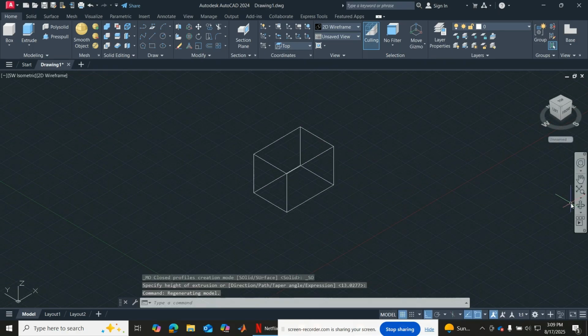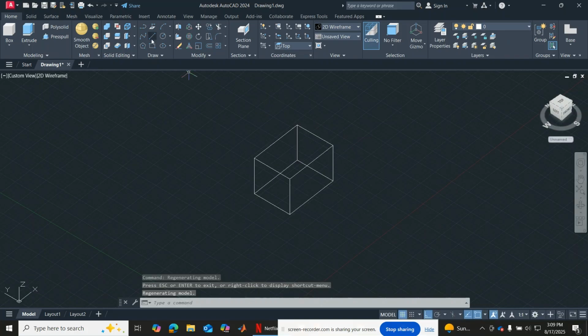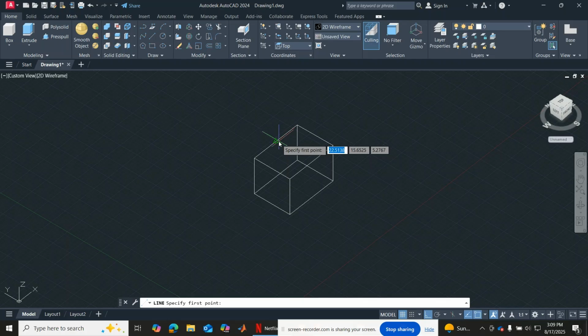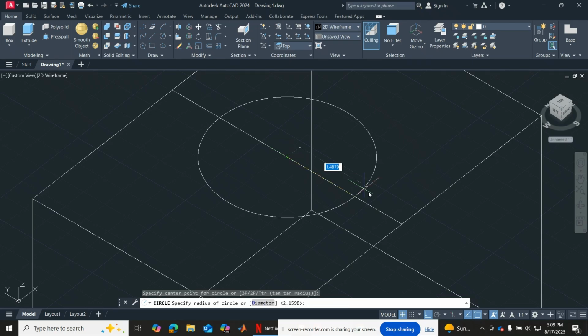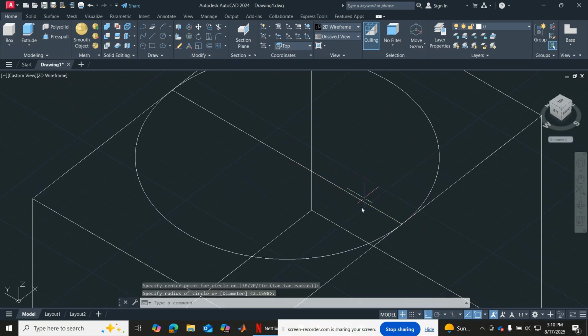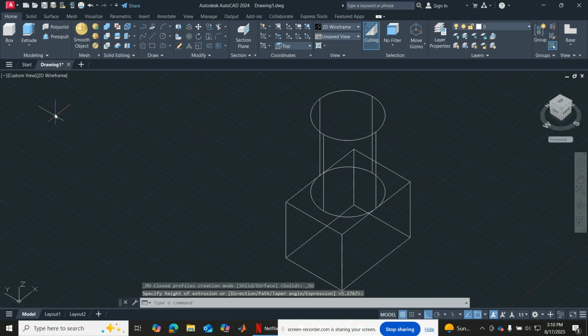Okay, let's say I want to put a cylinder on top of this box. So I can take a line and draw from this center here to this center here. And then I can take a circle. I can draw it from this center of this line here to this point here, right? Then I can delete this line. It was just guiding me. Then I can extrude this circle that is on top of this box and say extrude. So let's say extrude to there, right?